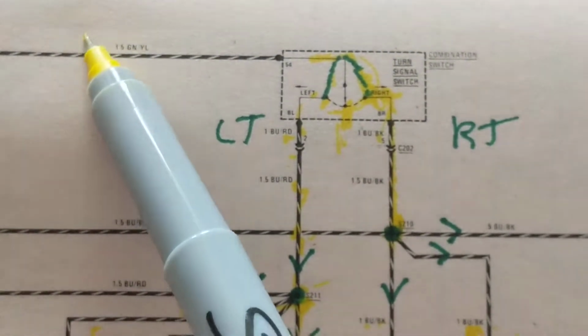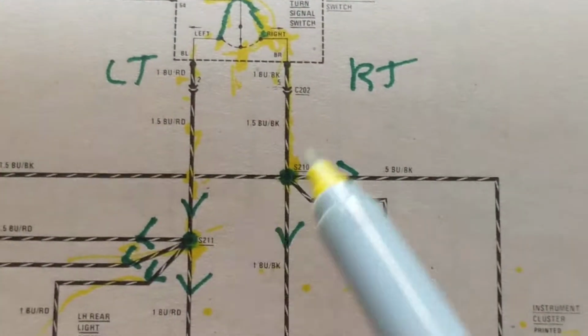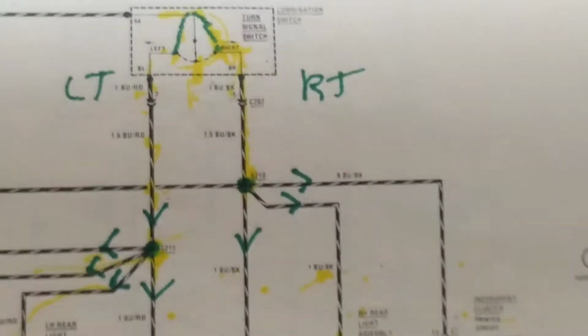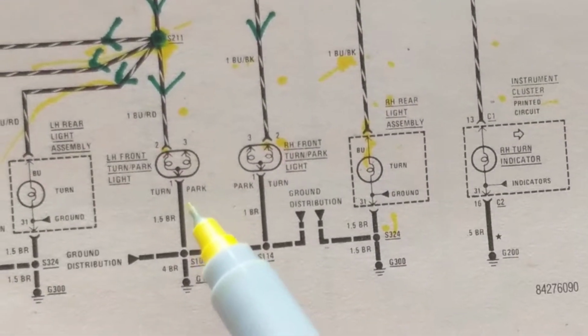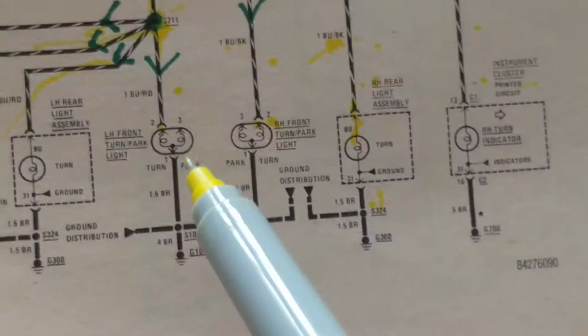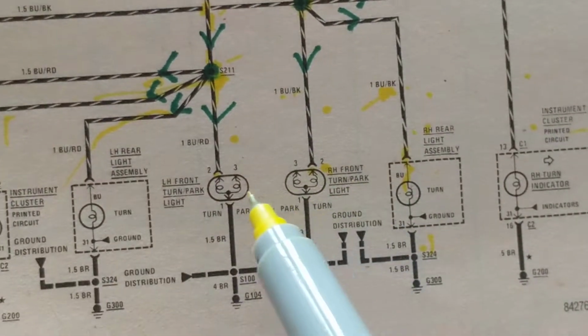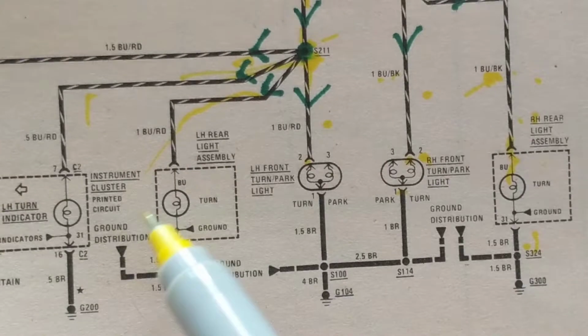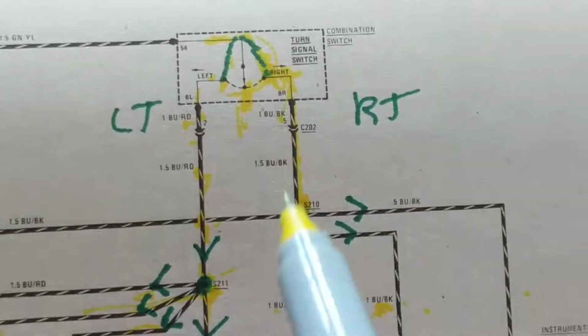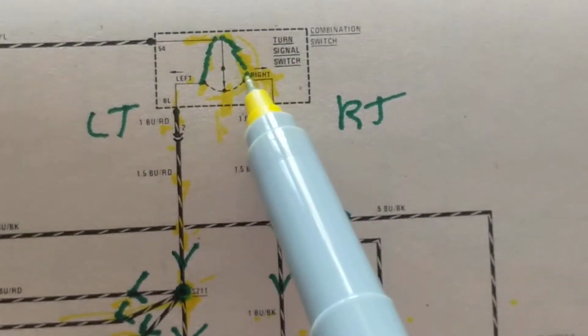If there is a fuse over here, then all of this will not work. So you look at all the symptoms. If one bulb is not lit, let's say the park, then obviously I'm going to say, okay, probably the bulb. But if all rear, park, and dashboard in the instrument cluster don't work, then I have to say probably maybe the switch doesn't toggle.